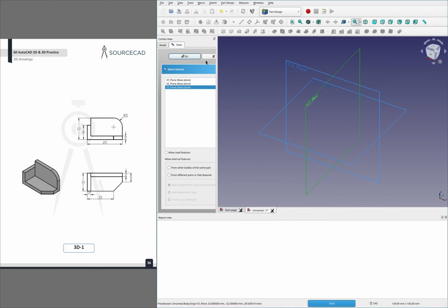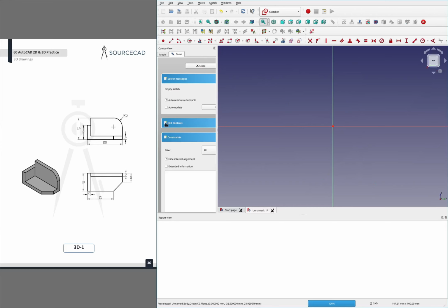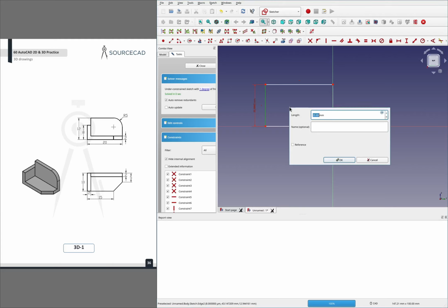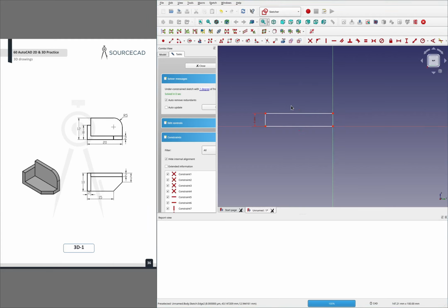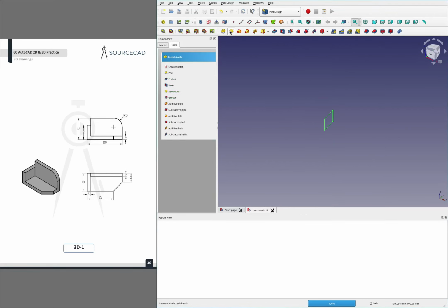Okay, so put a sketch on this face, and this first face here is just a square, so we'll make ourselves a square. And the vertical dimension, Shift V, and it is 8 tall. We're just going to be using the standard units here since these don't have units on the drawing. And then the horizontal dimension for this is a 10. And pad that a 2.